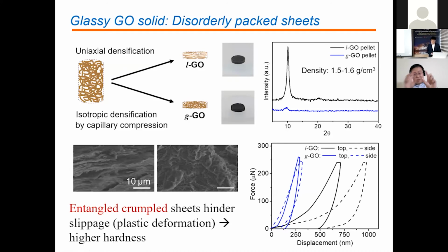For example, if the starting dough is more isotropic in shape, because the geometry sets the boundary of the wetted gel, and that physical surface is where evaporation will start, then you are generating a more isotropic capillary compression field. If you have an elongated rod, then when you dry it up, you're not going to get a glassy structure. You're going to get a thin wire that again has preferential alignment. Well, that's actually not a very good example. If I flip it, if you have a large disc and dry it up, then you're going to have a preferential stacking.